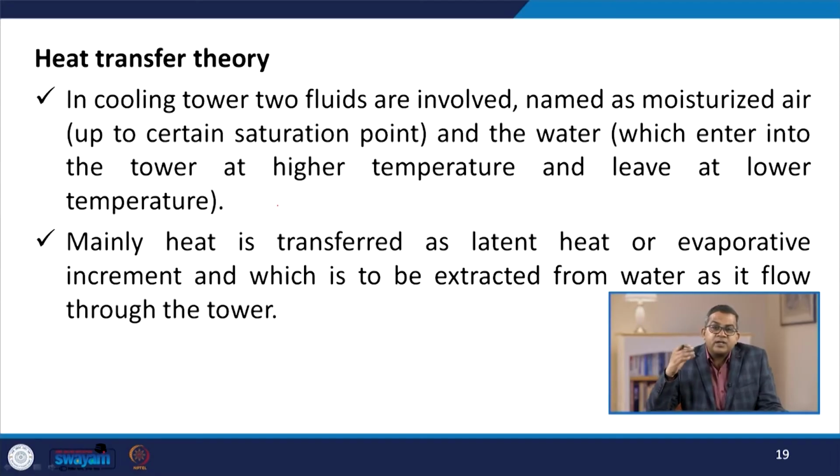Now, let us talk about the heat transfer theory. In a cooling tower, two fluids are involved. One is moisturized air, that is, air up to a certain saturation point, and the other is the water, which enters the tower at a higher temperature and leaves the tower at a lower temperature. Mainly, heat is transferred as latent heat or evaporative heat, which is to be extracted from the water as it flows through the tower.